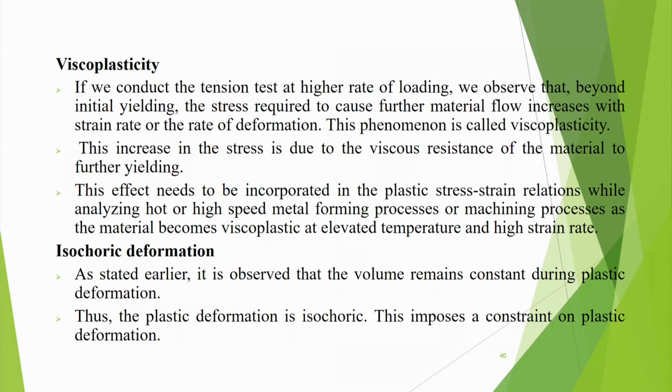This effect needs to be incorporated in the plastic stress strain relations while analyzing hot or high speed metal forming processes, or in machining. In machining also the strain rate can be very, very high, particularly in high speed machining. And this effect is more prominent if the temperature is also elevated. So, when you have elevated temperature and also high strain rate, then these effects have to be incorporated.